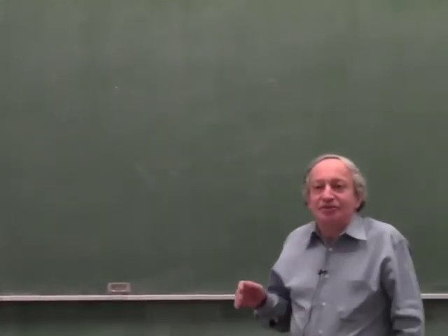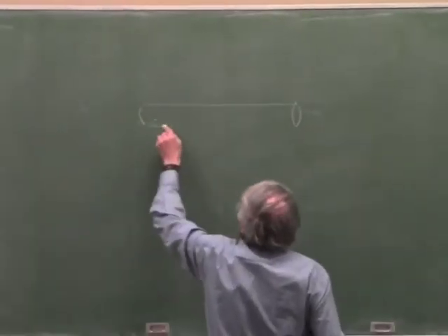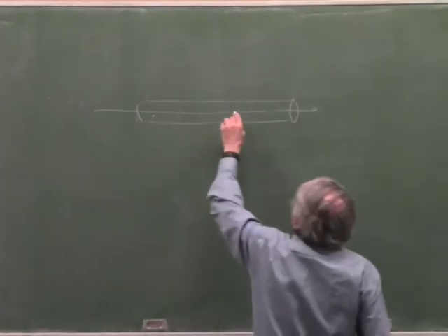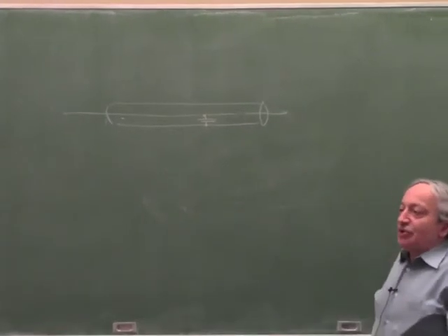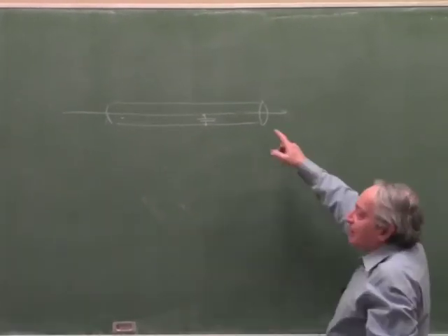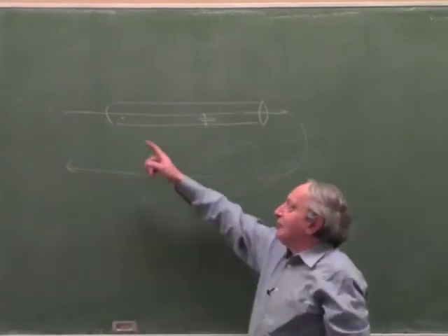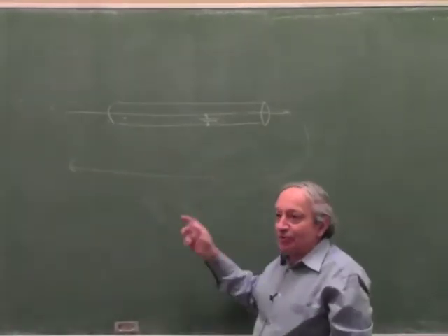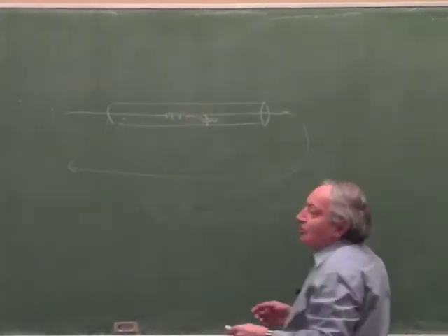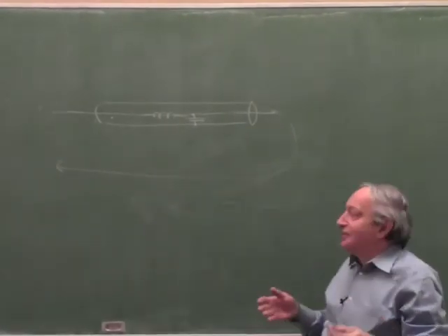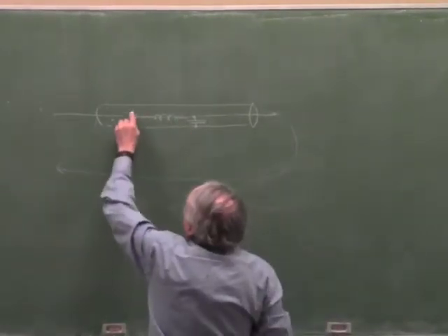A shielded wire is used without any consideration to impedances. If you take a shielded wire, there is some parasitic capacitance between the wire and the shield. There is actually also parasitic inductance, because if current flows through a wire, the current has to return somehow, and that creates a loop, which means there is inductance. So there is also parasitic inductance, although it's not obvious when you look at a wire. Why would a piece of wire have inductance? But it has.